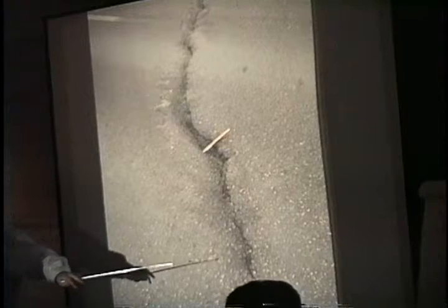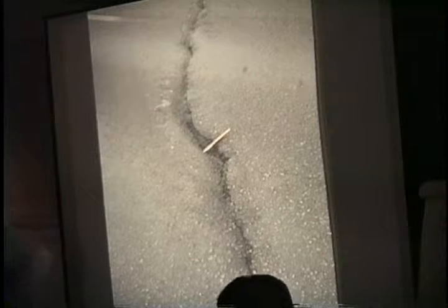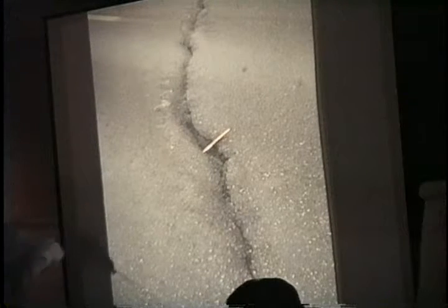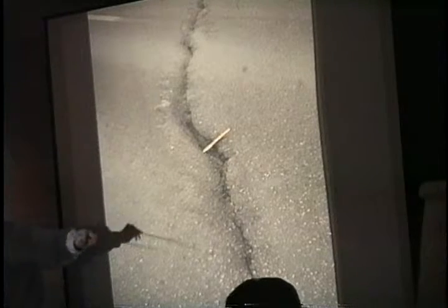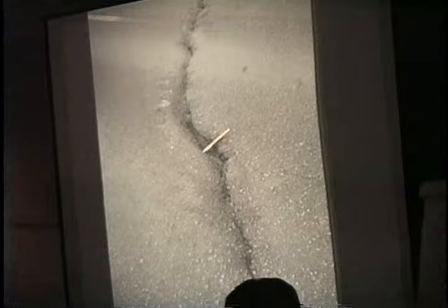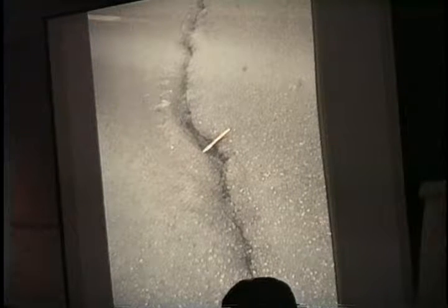What might you be able to do if this is accessible? Let's say this is only 100 feet or 50 feet long. Could you dig that out with a loader and maybe put some fabric in there to reinforce it? Or dig it out and put some lightweight material in there?